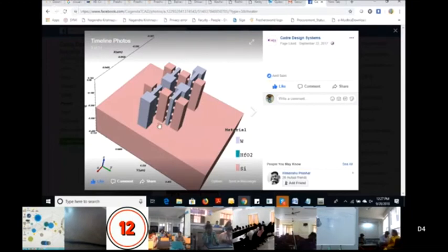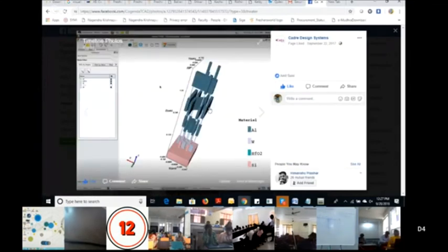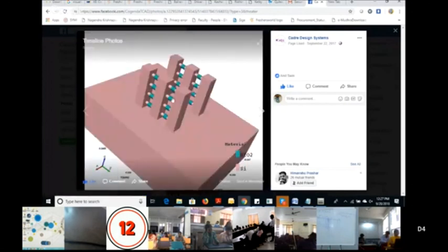The layout remains the same, but in the process we have to pass a parameter for how many stackings we require, how many nanowires we require, like 1, 2, 3. This is 4 nanowires. 4 nanowires are stacked. This is a complete circuit. How many nanowires are required is impossible to control from the layout, but from the process file we are able to control this. Some parameters use the layout: we can control a dimension, we can control the doping, but the architecture we have to write in a script, the process script, how the architecture will look like.